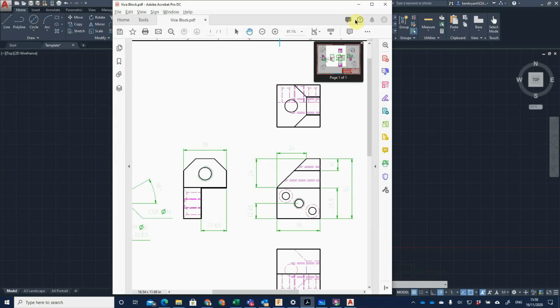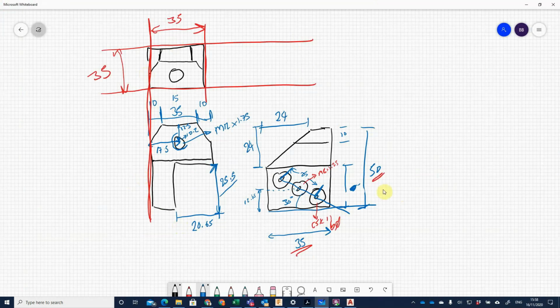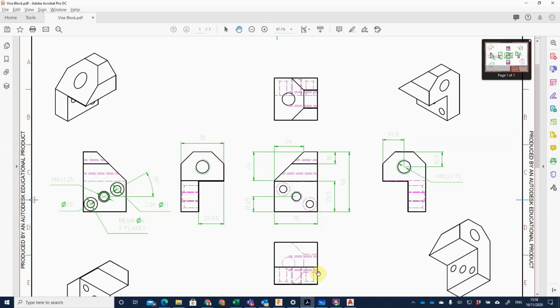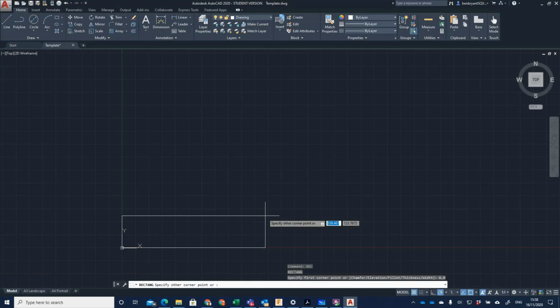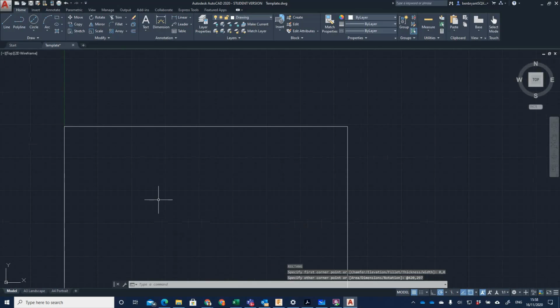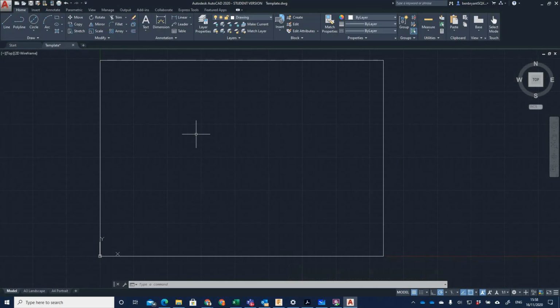So just recapping, we're changing this drawing here. Okay, I've made some notes with my drawing as well, on how to get it into the correct format. So first thing I need to do is use the rectangle command, and put in from my datum of 0,0 my page size of A3, so I can stay within the correct zone while I do my templates and my output of my drawing later. So again, using the construction line, holding shift to lock to the 90-degree axis, I'm going to make my construction setup.